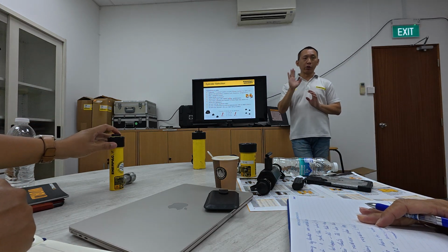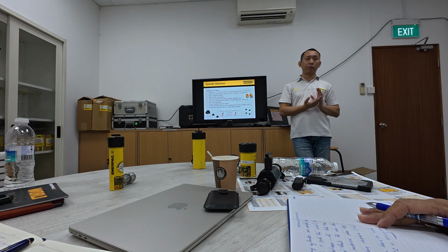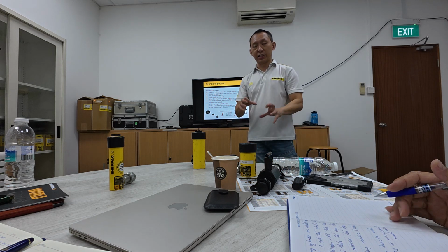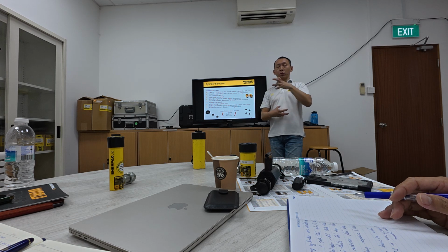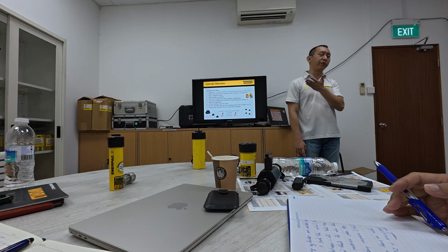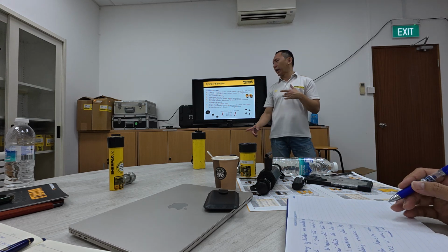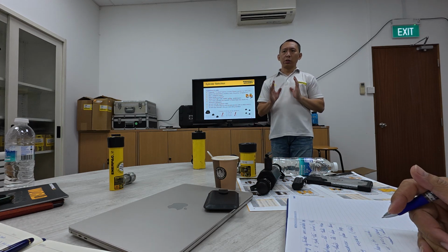When you take side load, because it tilts, it will definitely scratch the ball. Like this type of RC cylinder design, there's a bearing top and bottom, so it can take some side load, I think 12% if I'm not wrong. Some of the high tonnage cylinders can take up to 5 or 6. So it depends on the type of model.